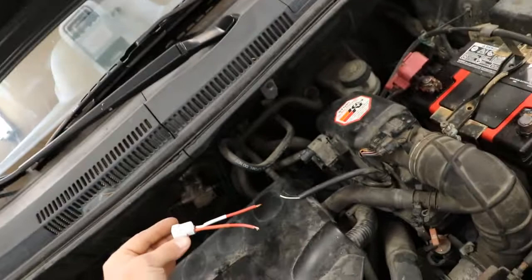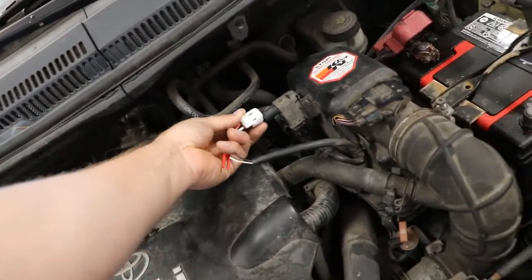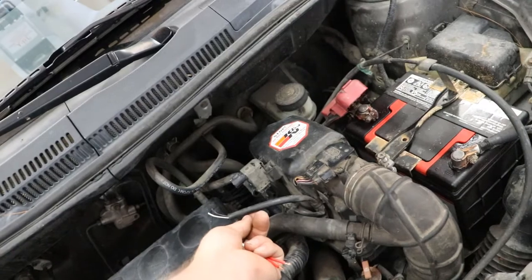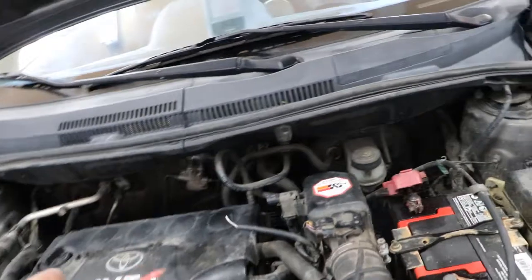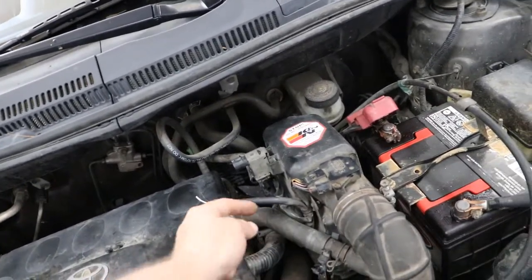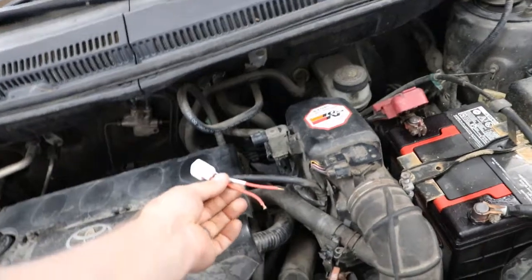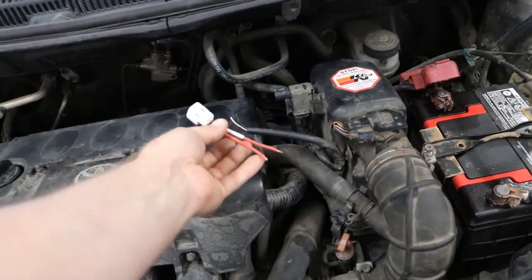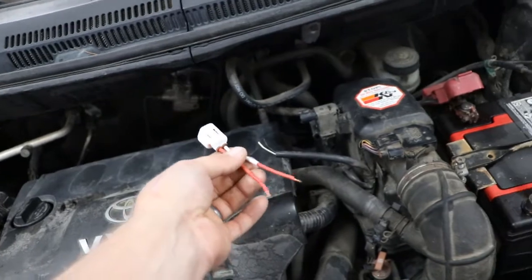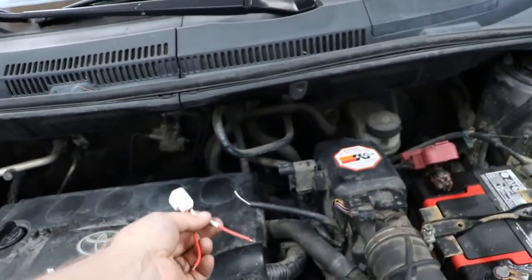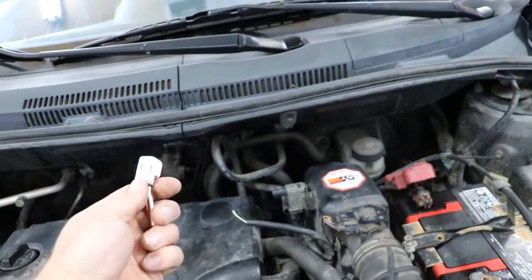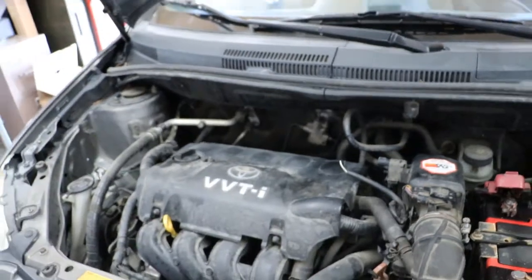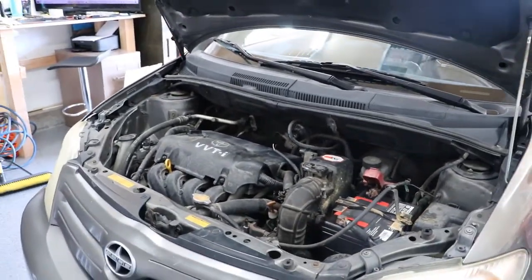So I got this piece. Now the next thing I'm going to do is, because I gave myself a lot of room to play here, it's going to be really long and goofy looking. So I'm going to cut down the wires a little bit and then connect it, so it's around the same length here. I'm going to strip these wires. I'm going to cut down this housing a little bit to reveal the wires. So cut them down a little bit. When I'm done cutting them down, I'm going to splice and actually solder these wires on. Heat shrink around it, with some more heat shrink like I have here, and I'm going to seal the system well and make sure it has a good connection. So that's the next phase here. We're going to go ahead and attach the new wires and get this thing with a good connection again.